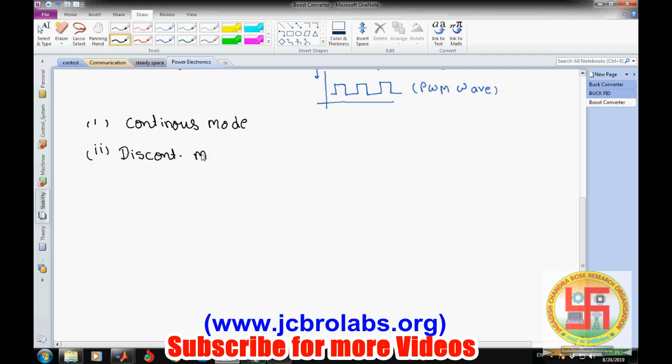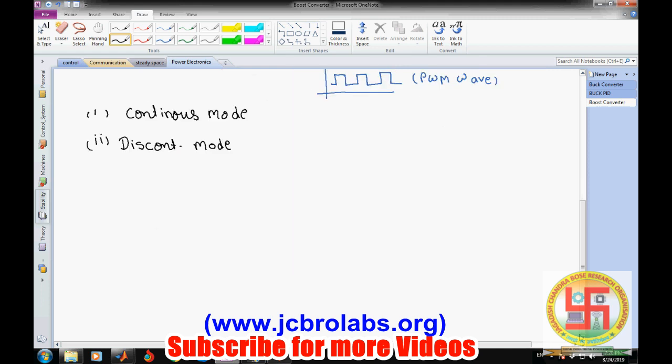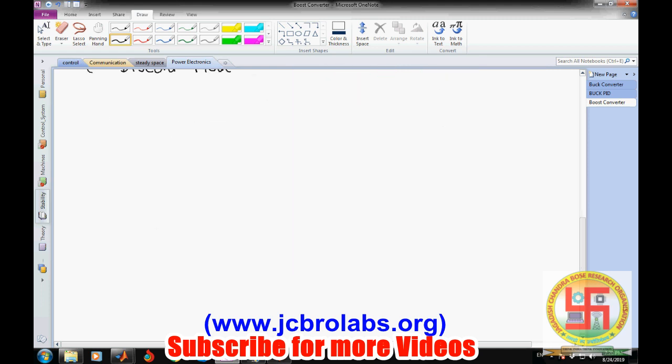So our main requirement to operate this boost converter or a DC to DC converter is to operate this entire circuit in a continuous mode operation. Only then we will get the satisfactory value of the output. Otherwise, this output relation will not hold. Okay, so we will be talking about the design parameters for continuous mode operation only.